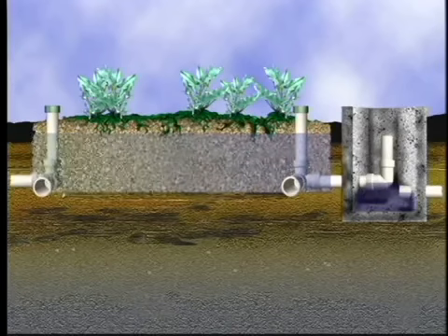Disinfection systems are used as an additional safeguard against pathogens in the wastewater. Disinfection systems are placed between a secondary treatment unit and a land application system. Three methods of disinfection are available: chlorine, ultraviolet light, and ozone. Chlorinators are the most common type of disinfection system. This system relies on a monthly addition of chlorine tablets to ensure disinfection of the wastewater.